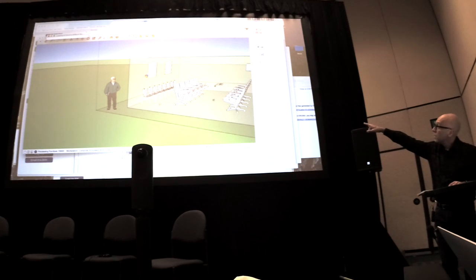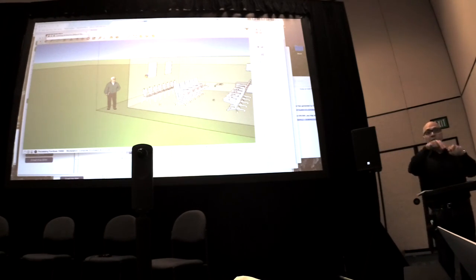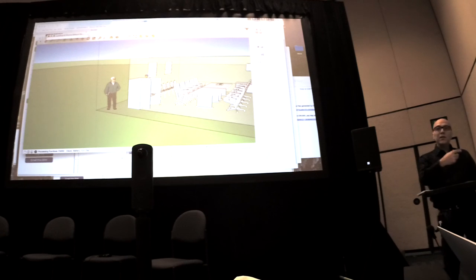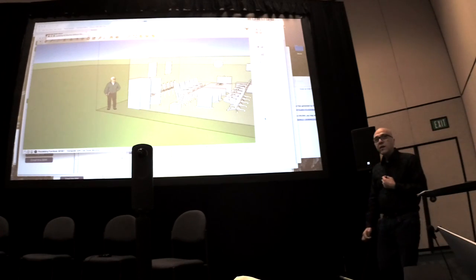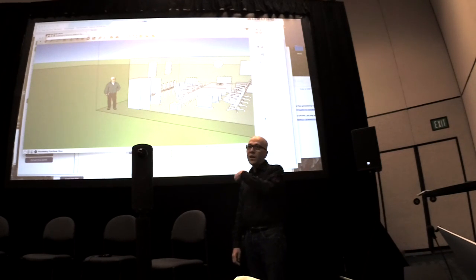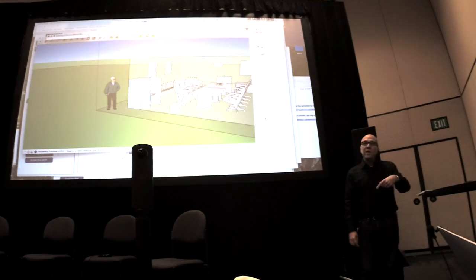So these are actually coming in, and those objects have the VA data that I showed earlier embedded in them. SketchUp at this point is a BIM tool because it has data with a name. I don't have to go in there and name that to be in alignment with the VA requirements. So this is kind of design automation as well. In a way, yes, it's a design automation of the requirements, the functional requirements that we still have to design with this. But it's automating that part.